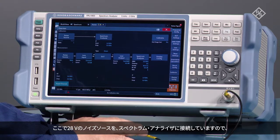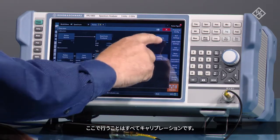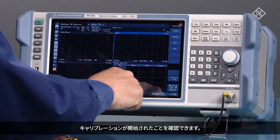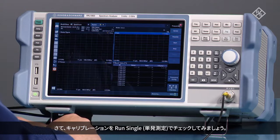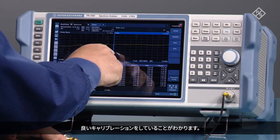calibration. We have connected a 28-volt noise source right here to the spectrum analyzer, so all we're going to do now is calibrate. And we can see now that calibration has started, and we can see the progress right here, and we can see it's calibrating. It will switch to ready when we are done. Okay, so now let's check our calibration by selecting Run Single. And we can see now that we have a good calibration.